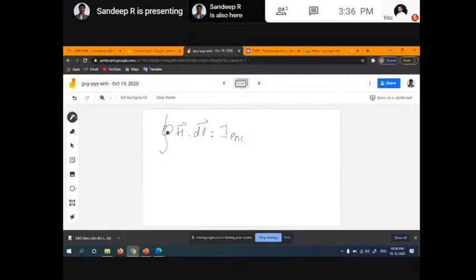We know that I is equal to the surface integral of J dot ds, so I can write this as the surface integral of J dot ds. So the circulation of H would give me the current enclosed by the path. Using mathematical notation, curl of H is equal to J.